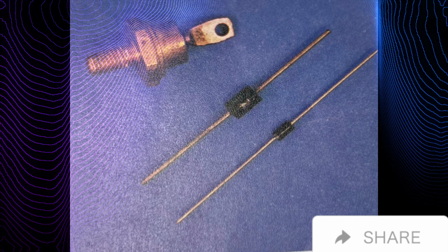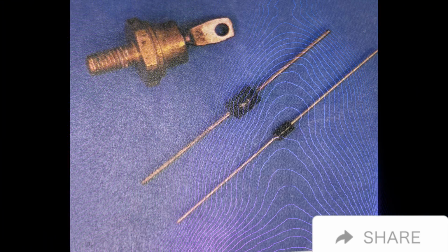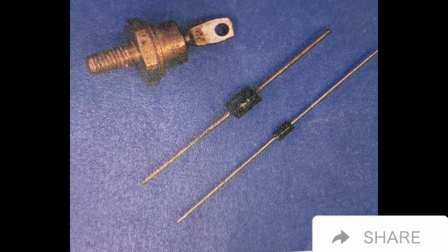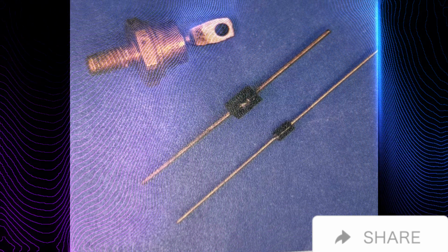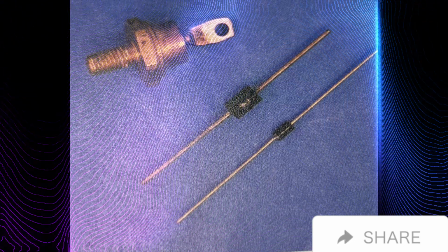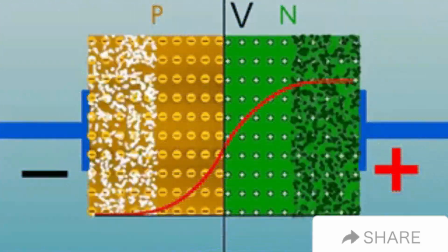An ohmmeter can always be used to determine the proper lead identification. If the polarity of the ohmmeter leads is known, the positive lead of the ohmmeter must be connected to the anode to make the diode forward biased.